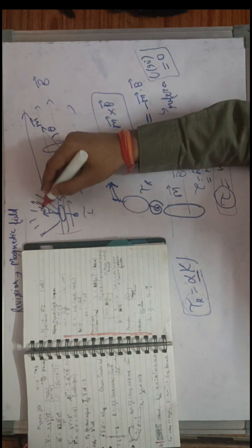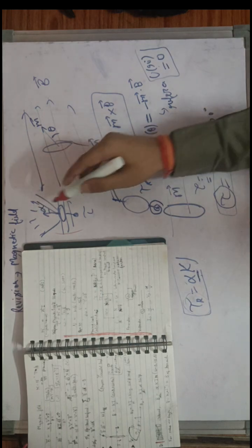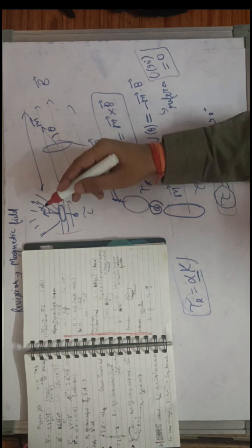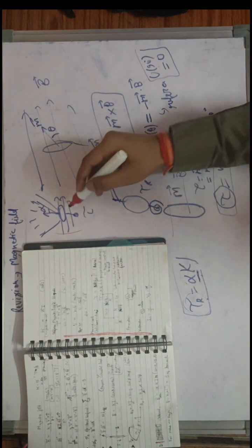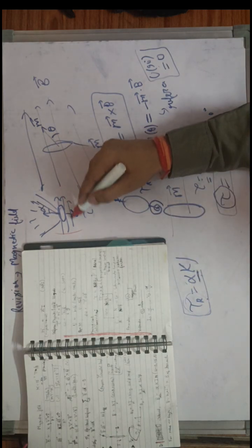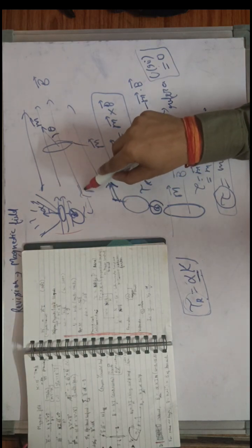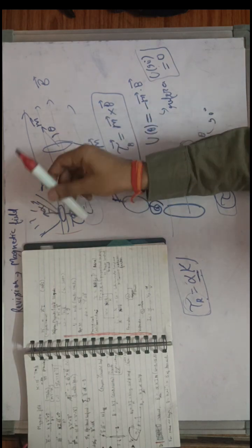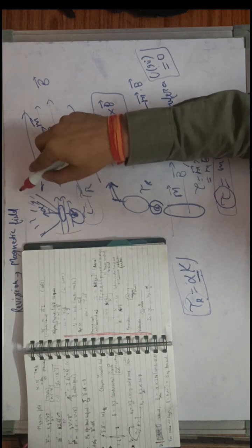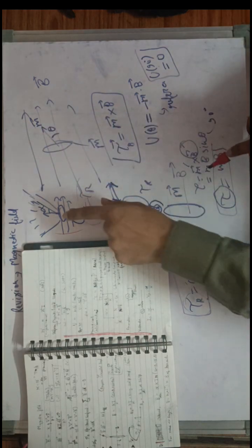When some alpha angle is produced, there will be a restoring torque due to the spring attached to it. When this becomes equal to the deflecting torque, the coil will stop at a reading value, and this tells the reading of the current.